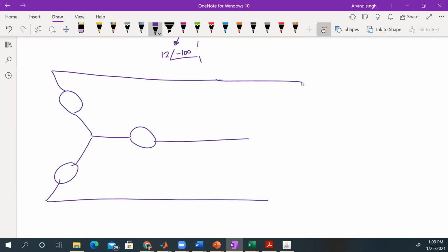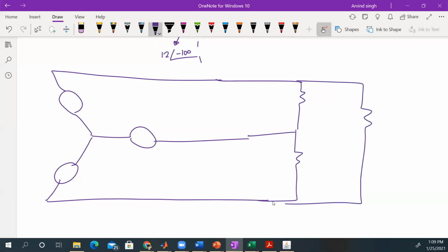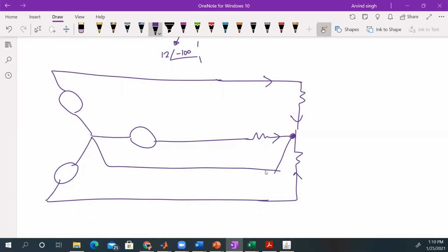and you want to connect a load to these, so you have one here, one here, one here. Let me do it as a star, since that will be easier to see. So we connect it to a load. Then the currents coming here all sum to 0. So I do not need a return path. Right? I don't need that return path.